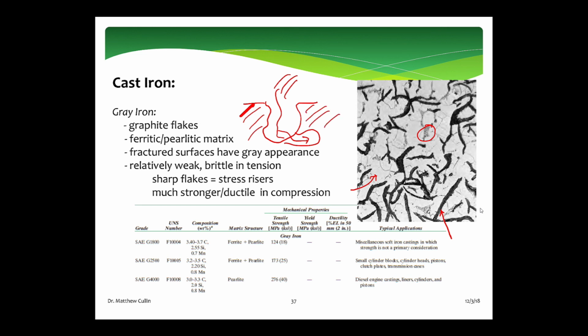You need your metal to flow into all the little spaces of the mold before it solidifies. As a result, having lower melting temperatures saves us a lot of money and lets us mold more complicated structures than if we were talking about a cast steel.